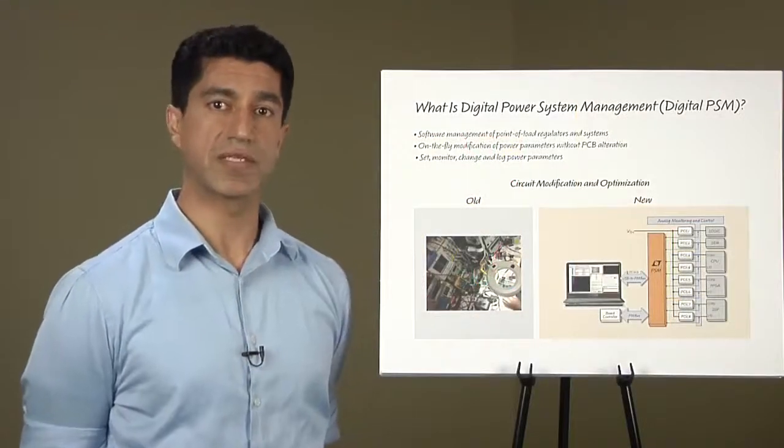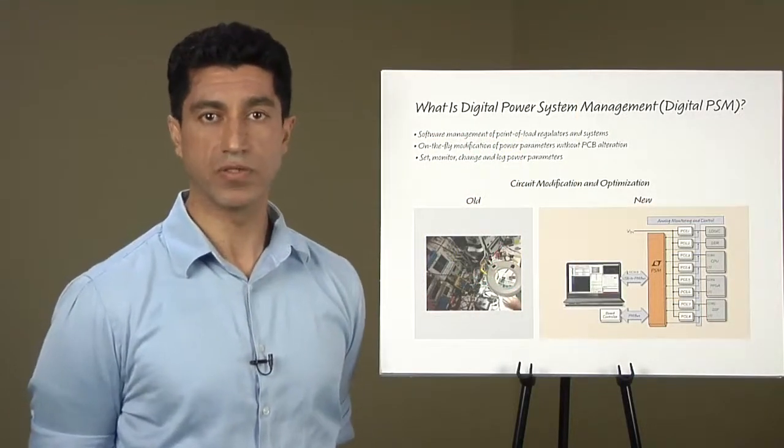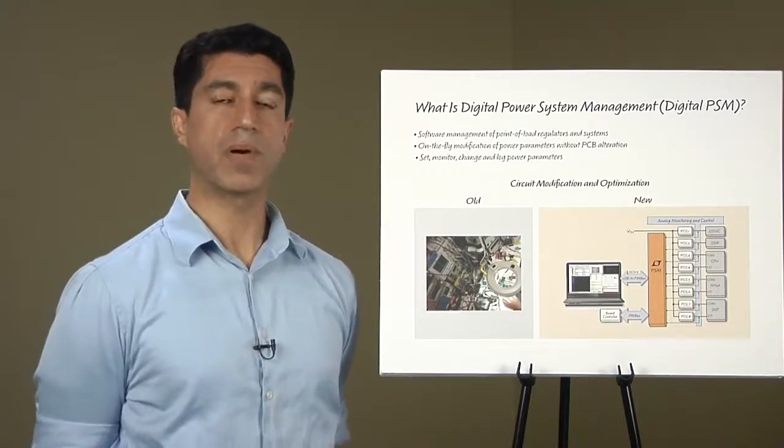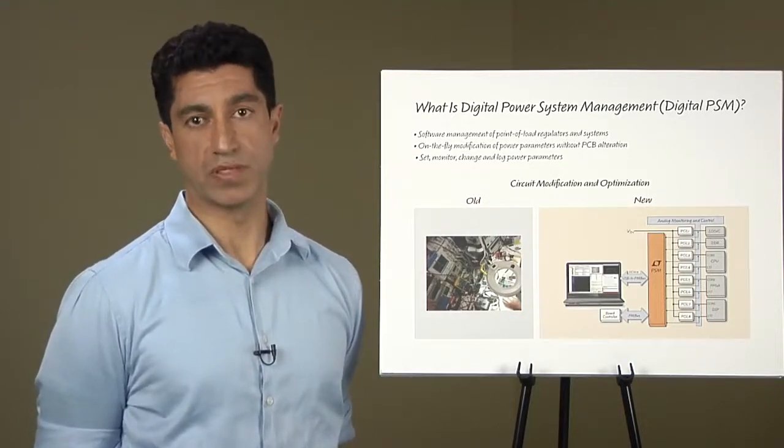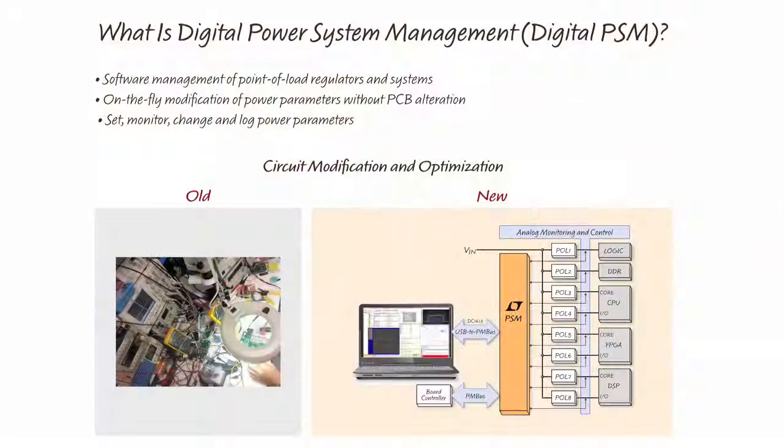To simplify these tasks of managing power, there's a growing trend to configure and monitor power over a digital communication bus. In other words, implement telemetry capability to set, monitor, change, and log power parameters. This technique is frequently referred to as digital power or digital power system management, or PSM. It allows systems designers to simplify and accelerate system characterization and optimization during prototyping, deployment, and field operation.